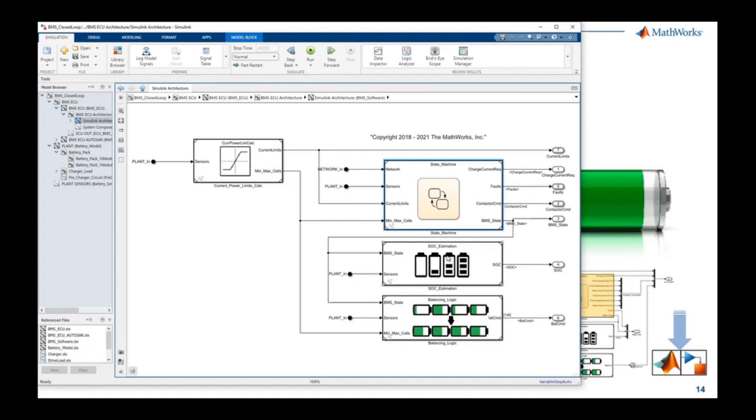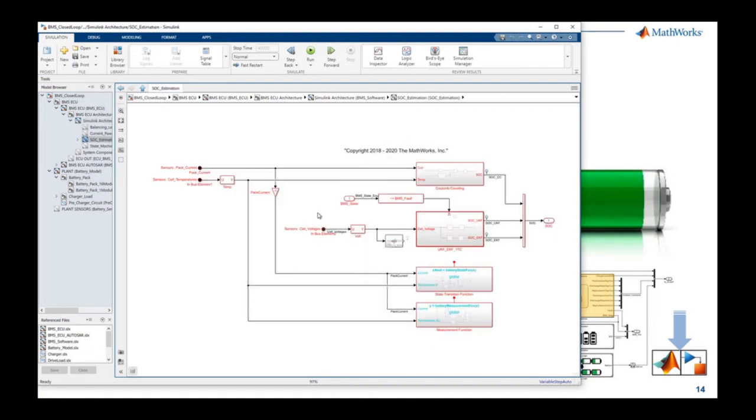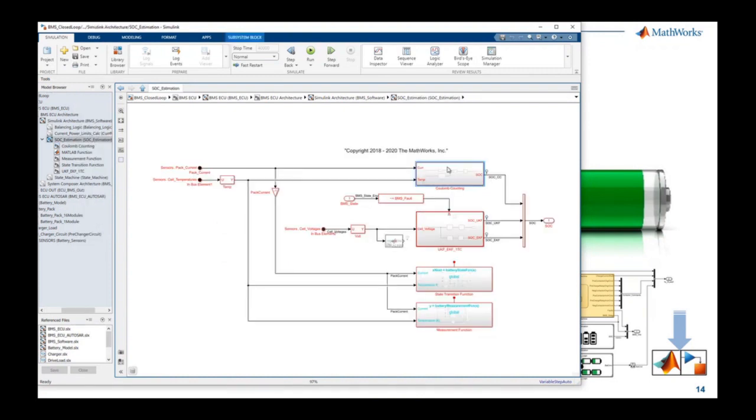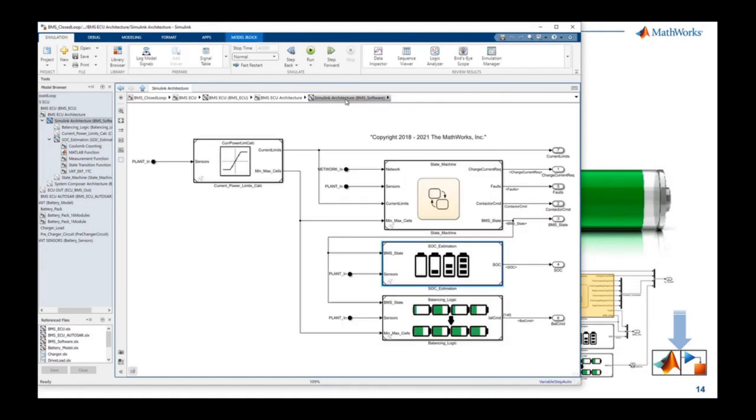And perhaps if I just go in the SOC estimation, just for your information. So here, in order to estimate the state of charge of the battery, there are many techniques to do that. The one I showed you before with the Coulomb method is also the one that you can retrieve there. So you will just integrate over time, okay? But then there are other models that can be done using Kalman filter, using also neural network approach, and so on and so forth. And this is just an example of what can be done, but there are many different techniques in order to do it.